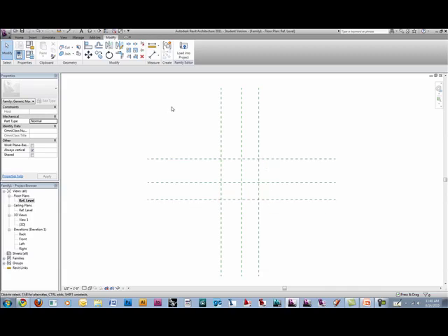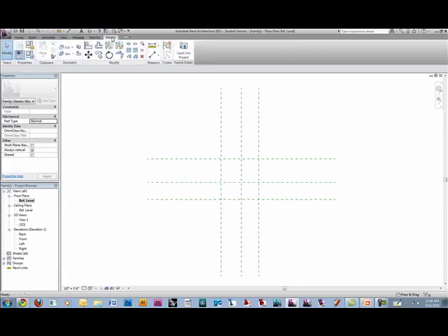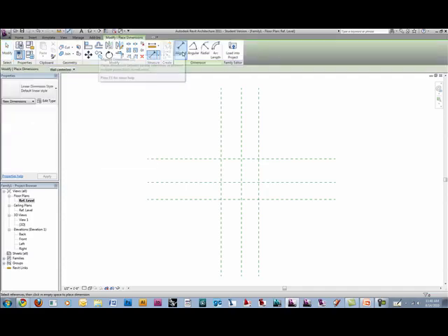Alright, so how do you tell this to be parametric? We're going to use the measuring tool. You can find them either on the Home tab, Annotate tab, or under the Modify tab. The Modify tab is open more than the rest of them, so we'll just use this one. You can do a bunch of different ones: arc lengths, radials, angulars. We're just going to do a line because these lines are parallel, no big deal.